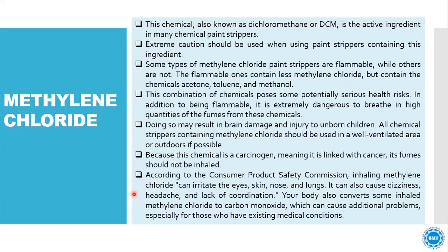This combination of chemicals possesses some potentially serious health risks. In addition to being flammable, it's extremely dangerous to breathe in high quantities of the fumes from these chemicals. Doing so may result in brain damage and injury to unborn children. All chemical strippers containing methylene chloride should be used in a well-ventilated area or outdoors if possible. Because this chemical is a carcinogen, meaning it is linked with cancer, its fumes should not be inhaled.